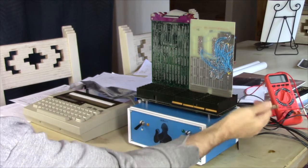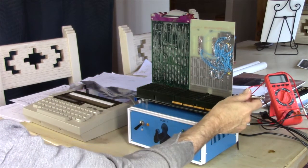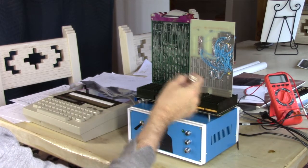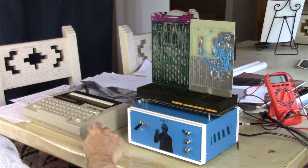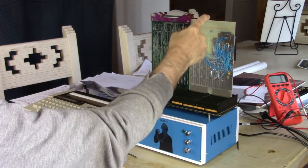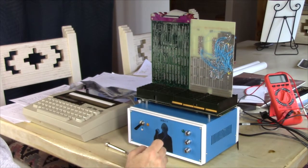The first three slots on this card are CD slots. These are all AB on this side. First three here are CD, and then these are AB. So you could put, let's see, 1, 2, 3, 4, 5, 6, 7, 8, 9, 10 more of these dual width cards onto this bus. This is an H9278A, by the way, for those keeping score. But this can plug into either an AB or a CD because the power and the ground are on the same pins on both, and I'm not using any other data lines or anything.